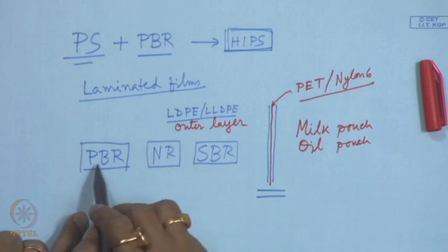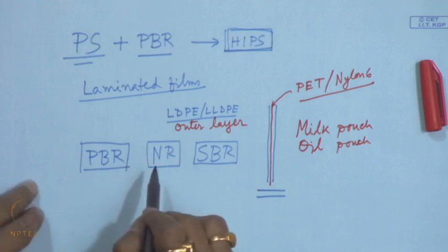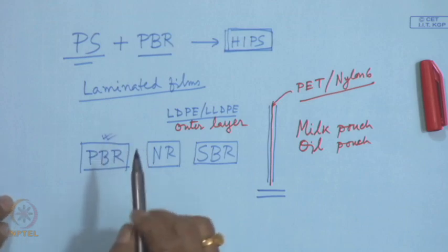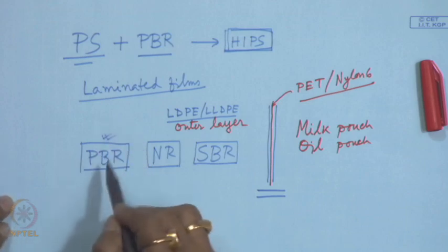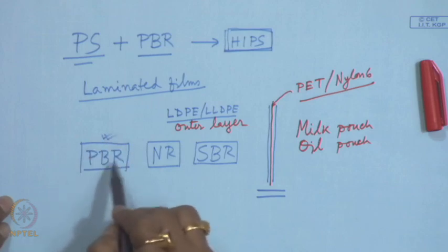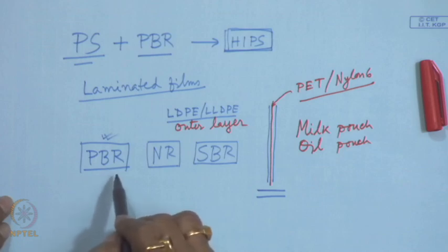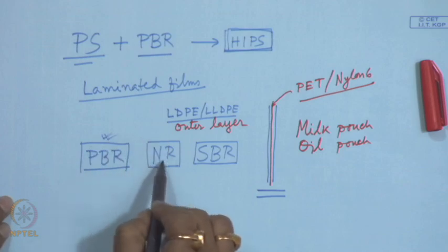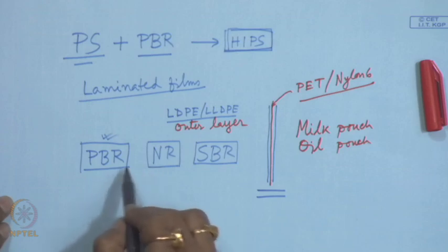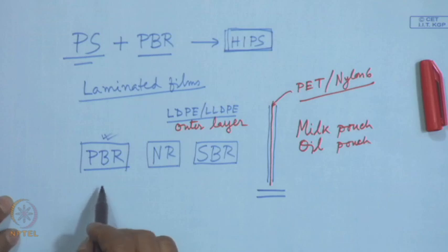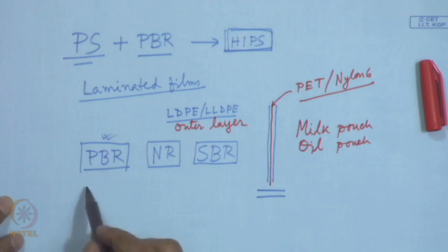So, processability, I mean the compounding of this polymer as well as shaping and fabrication of the compounded polybutadiene rubber with some other additives, that is not good. So, in order to improve the processability, we can use a little amount of natural rubber or SBR with this polybutadiene rubber. Similarly, processability of other thermoplastics, polyolefins or other polymers, say condensation polymers.